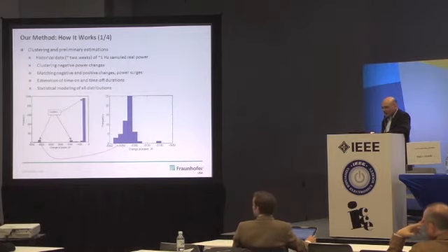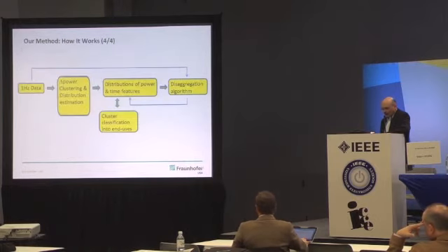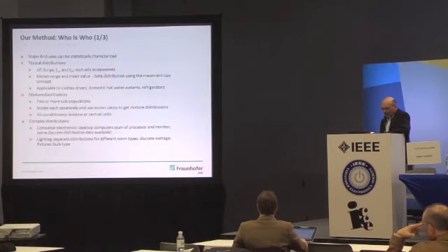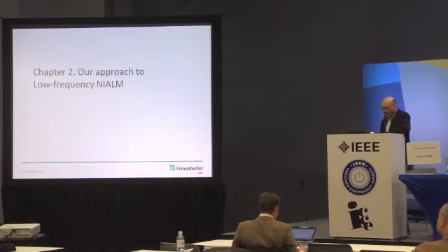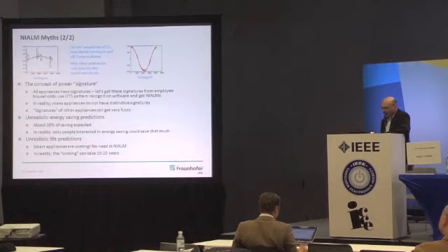Well, and that's becoming more difficult with switch-mode power supplies, right? They also have significant inrush current. Yeah, many consumer electronic devices indeed have this inrush current, but the problem here is related to the frequency of our sensor. If it is measured every minute, for example, it will not be seen. It will just move out.